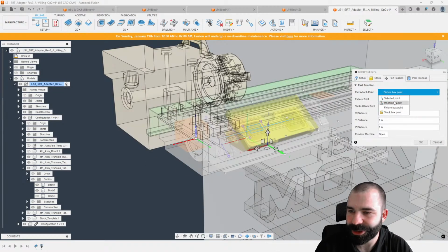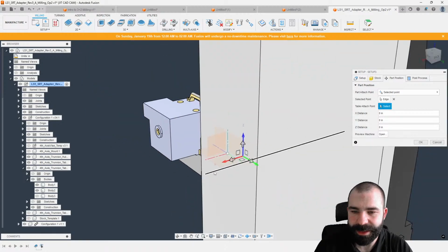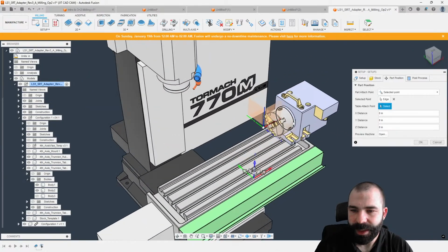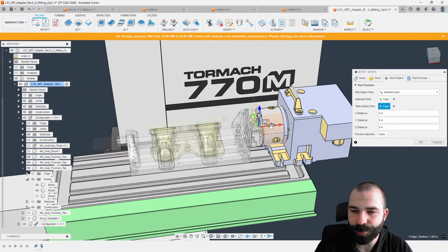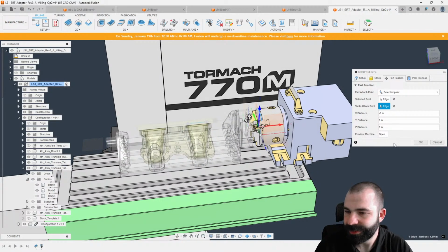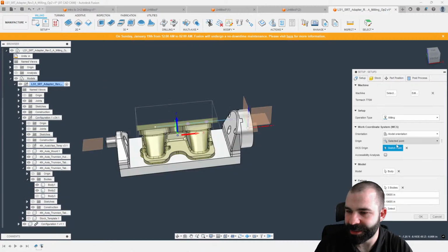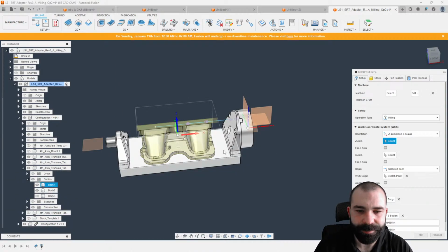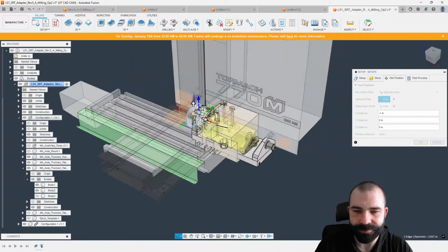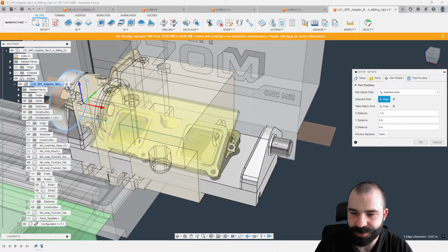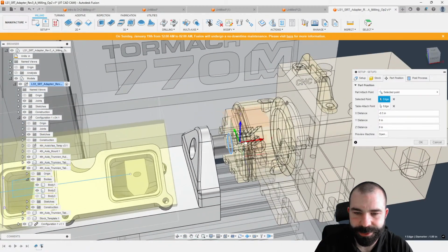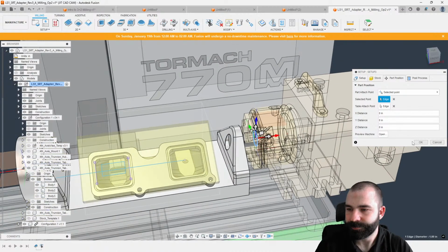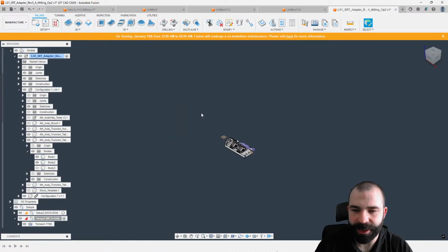So now we can go selection. This. Leave up to this guy. Beautiful. I assume you probably put this in the opposite direction, but I think we're going to be okay for this. What I would actually need to do is pick Z, pick X, flip X. Now attach it back the opposite way, right? So I want to attach based on here. Put that in that lovely little 3-jaw chuck. And there we go. We should have our part on the table now.